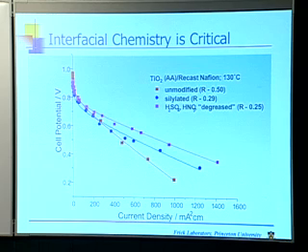A massive improvement. And we did the same thing now as shown on this transparency, but instead of carrying out a series of degreasing steps, we carried out a set of acid washes. Started with the poor material, took it through a series of mineral acids. Actually, we had acetic acid early on in this process, ending up with water. And again, you get a wonderful response. So it's beginning to look like there's something about the surface that isn't so good.